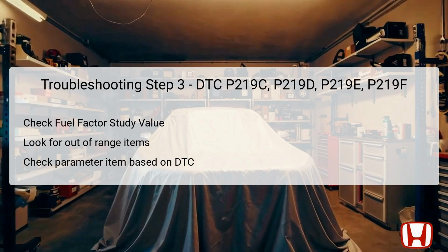It's vital that the technician selects the parameter item directly associated with the stored DTC to ensure accuracy during this inspection. This logic-driven approach allows for pinpointing issues to specific cylinders while also validating the PCM's feedback on its air-fuel target ratios. Evaluating these parameters is instrumental in confirming whether a cylinder's air-fuel mixture needs further assessment, or if other components, like the injector or ignition systems, might also require inspection.